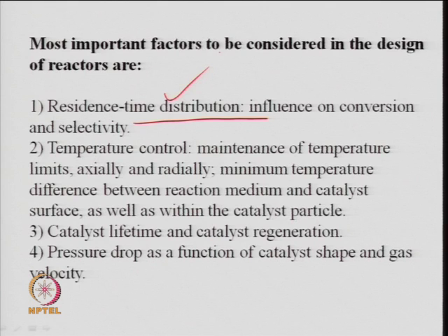So, this is again an important issue for the design of a reactor and the selection of a suitable regenerator, and a reactor cum regenerator system for a process, especially when the coke deposition on the catalyst is very high, a significant amount of coke. So, 5%, 10% is the amount of coke which can be deposited on the catalyst just after a day. So, you have to look at that.